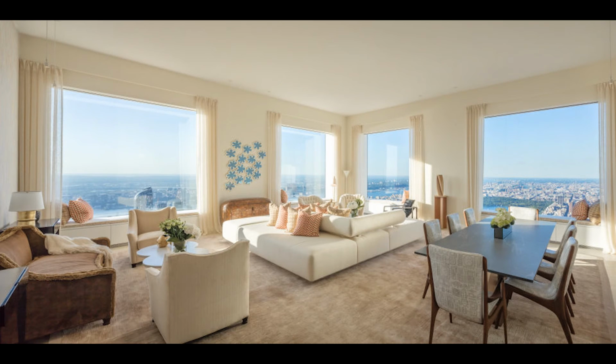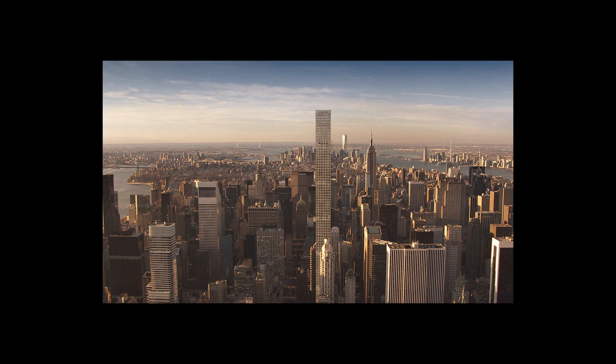The current building only has 104 dwellings and has appropriate services for this level of occupancy. Despite the column-free floor layout, it would be difficult for the building to serve more people in the future due to there only being 5 lifts. We suggest that more lift shafts should be added to provide a better long-term plan for this building.